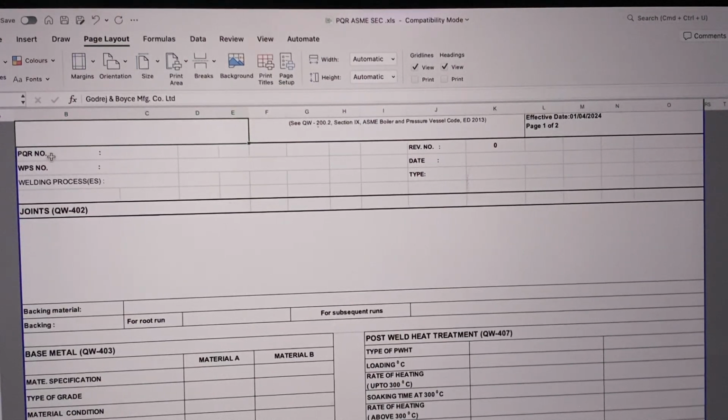For example, if we are going to have a shell of 30 millimeters and another of 40 millimeters, we will choose either 30 or 40 millimeter thickness and cut two plates of roughly 150 millimeter width and about 300 to 500 millimeter length, depending upon the number of tests we want to conduct on it and the test facilities that we have.